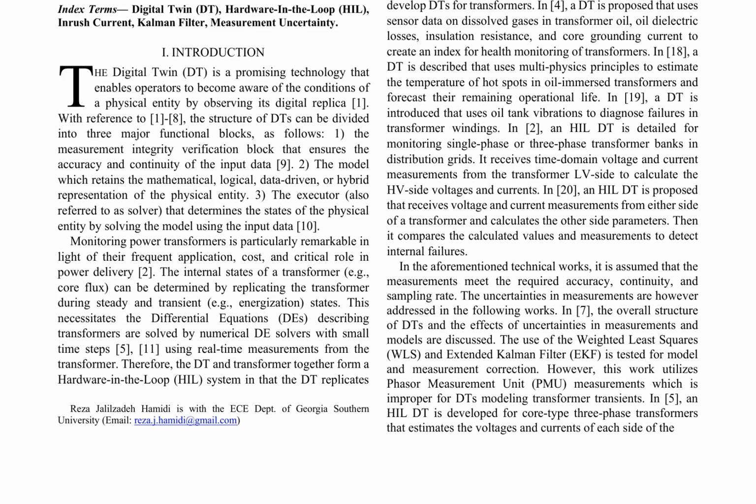The proposed method employs a recursive method for integrity verification of measured transformer currents, which is suitable for the modular development of HIL DTs. The differential equations, DE, describing transformer transients are relatively complex, requiring the use of numerical DE solvers with small time steps. This implies that replicating transformers with HIL DTs requires a continuous flow of accurate measurement samples with a high sampling rate.